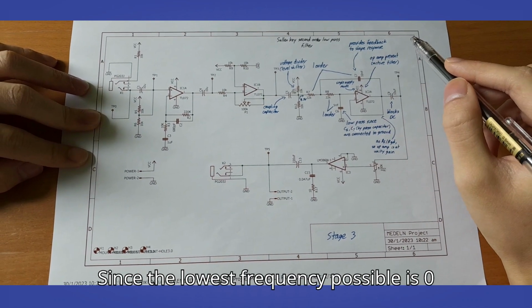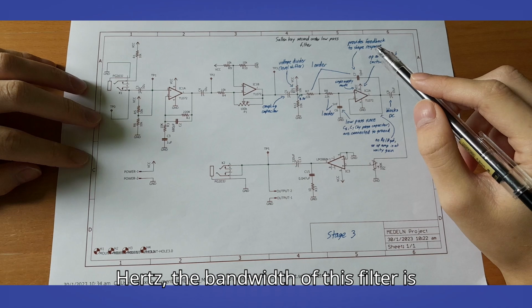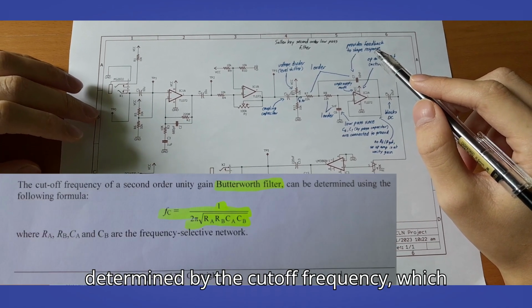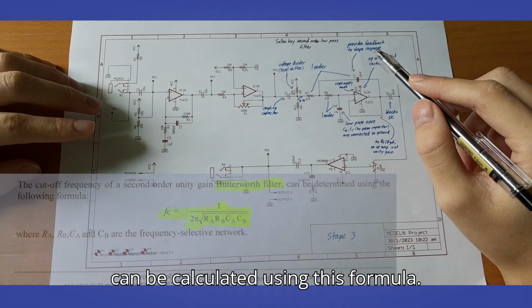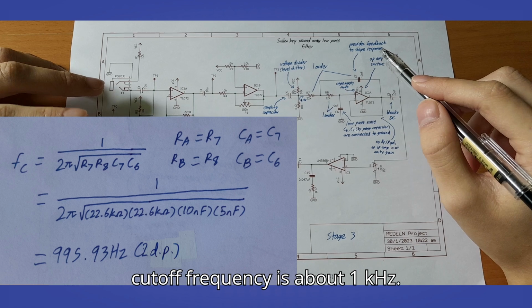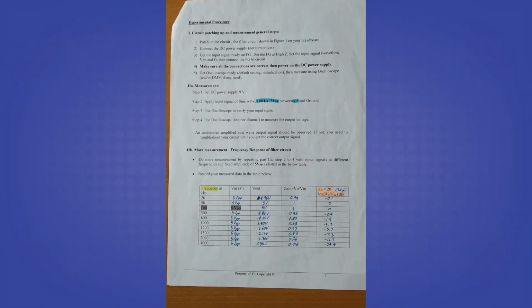Since the lowest frequency possible is 0 Hz, the bandwidth of this filter is determined by the cutoff frequency, which can be calculated using this formula. Using the values in the schematic, the cutoff frequency is about 1 kHz.